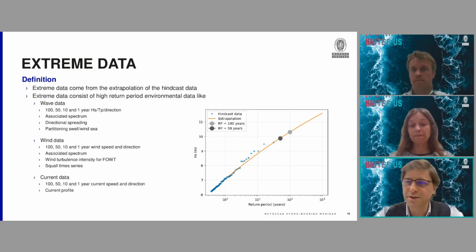Thanks again, Claire-Julie. And I think I have one question that is repeated twice. Again, I think it's for you, Claire-Julie. Do we always have to do time domain analysis for mooring calculations, or when do we opt between frequency and time domain approach? Generally, time domain is always more accurate for mooring analysis. Spectral analysis, as I said, for fatigue can be used really as a pre-project, but it's less accurate than time domain because it doesn't take all the parameters into account.